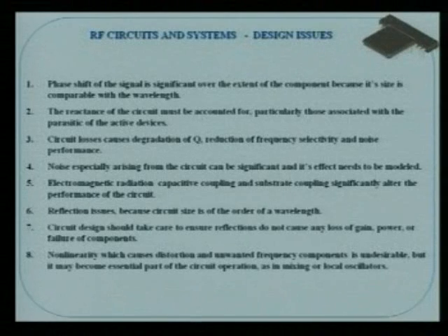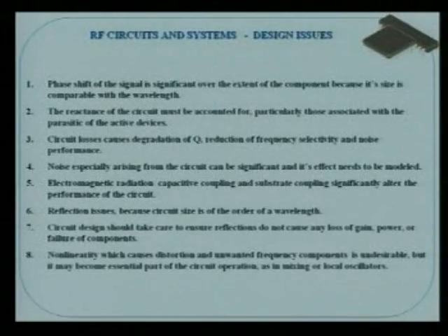When the impedances are not matched from the source to the load, then the signal will reflect back to the source. What will happen to the source? The source will be heated up and it will be damaged. And if the antenna is not matched with your LNA, that will happen. All your signal will go to the antenna side, so you need maximum power to be transferred to the load, and that is quite important.